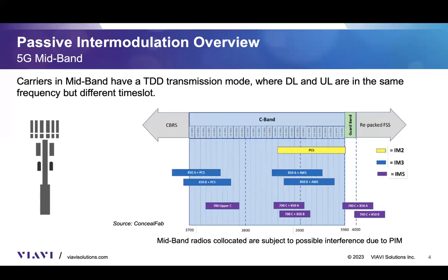Maybe not, unless there are adjacent carriers with a different frame configuration that might be affecting it. However, if we're collocating the 5G with LTE, we're going to have multiple combinations of different radio types that might be impacting my 5G signal. So it's important to really understand and make all these different radio certifications and PIM testing just to make sure that there's no PIM hitting into 5G.